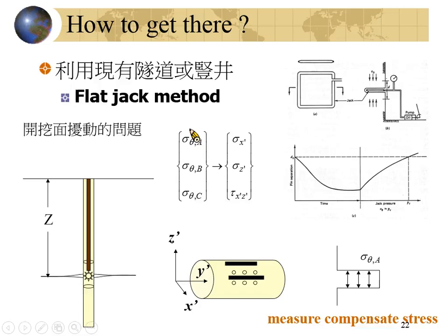The tunnel will have some micro crack effect around the tunnel wall because of the high stresses. You will have a high deviatoric stress. Do you still remember? It will be equal to 3 sigma V subtract sigma H, or 3 sigma H subtract sigma V. Okay, so you will have a high deviatoric stress. Then you will have a disturbance zone around the tunnel.